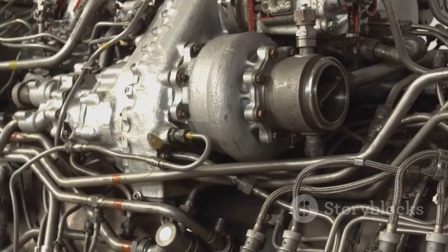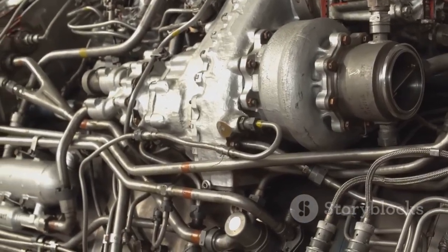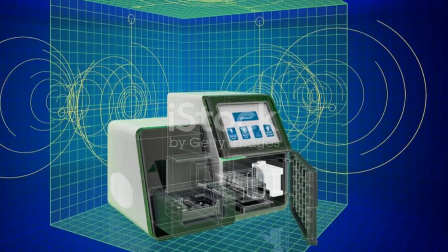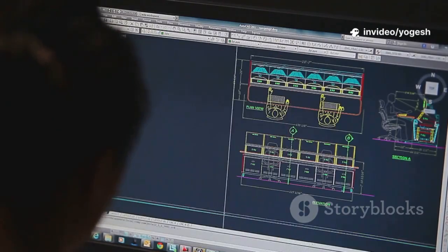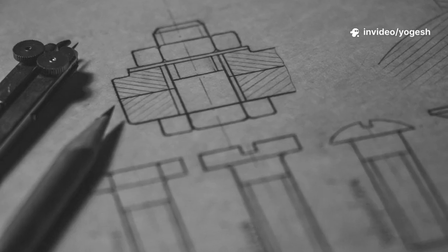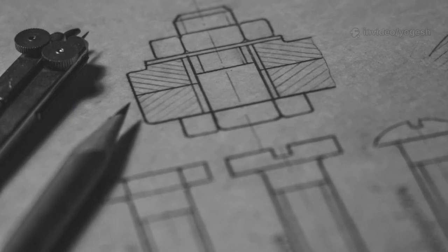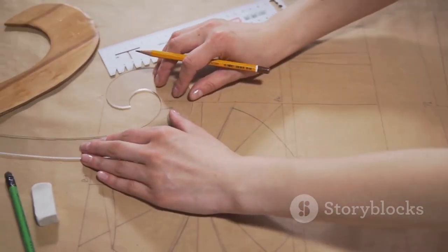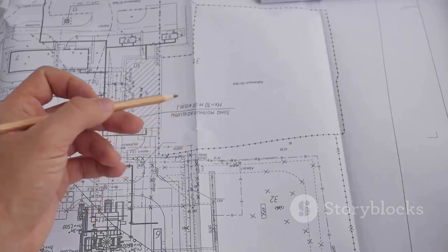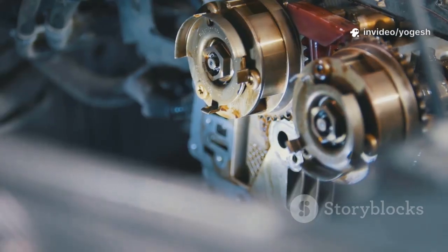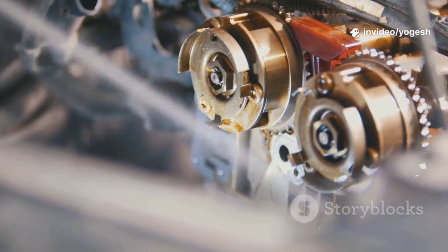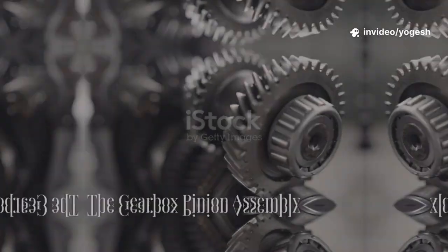For an assembly drawing, build the digital assembly, then create an isometric or exploded view. Generate the bill of materials and add balloons to link parts to the BOM. Include key overall dimensions if needed. Complete the title block before releasing the drawing. Every step ensures clarity and accuracy from design to production. The process transforms digital intent into real-world results.